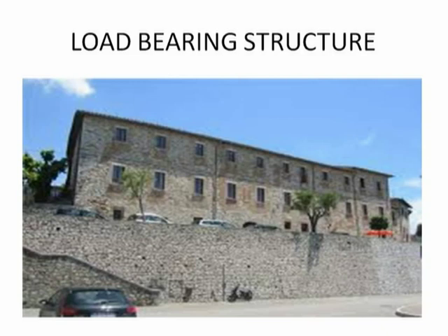If you construct this type of the load-bearing structure, there are two basic requirements. One requirement is that it must have a hard strata at the shallow depth. And second is that you can construct this type of the load-bearing structure up to a ground floor plus 3 story. It is not desirable to have a multi-story building with this type of the structure because there is a limitation of the thickness of the wall.